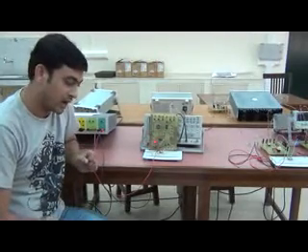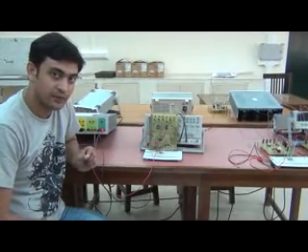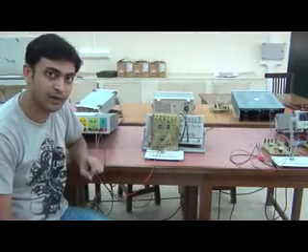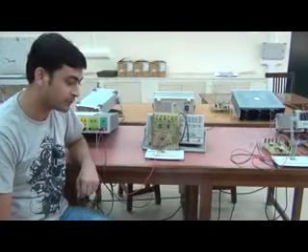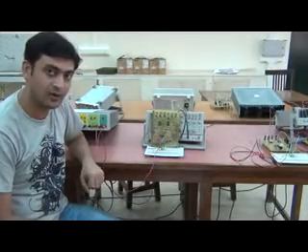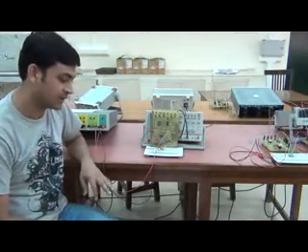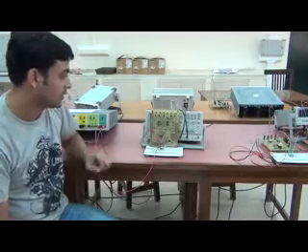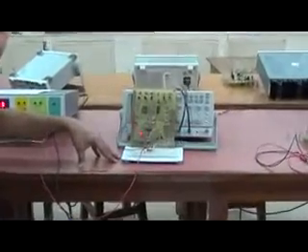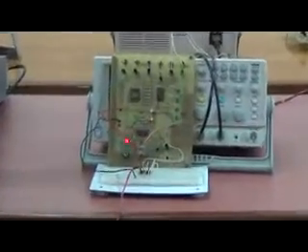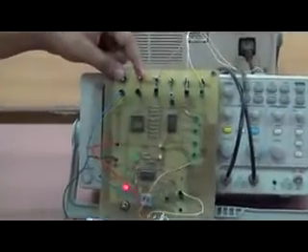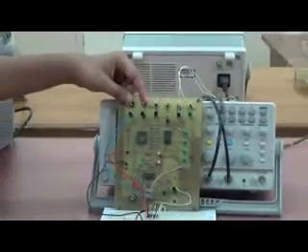The IC number 4027 is used for the JK flip-flop; the flip-flops are embedded on the IC number 4027. The pin configuration of this IC is given in the handout. The connections are made as per the pin configuration. Currently we are demonstrating the truth table for a single JK flip-flop. Here these two switches are taken as an input to this breadboard, or the JK flip-flop.